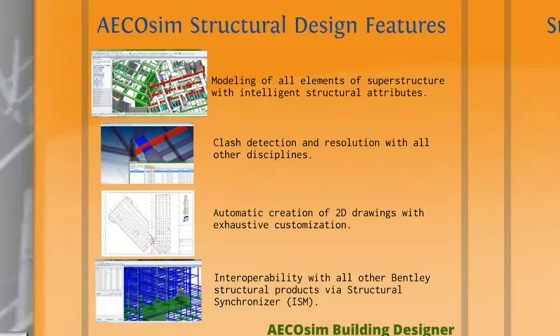applications. The second one, very important in terms of the coordination with other disciplines, and that's that you can perform clash detection between any two entities in the model, resolution as well, and that'll give us a chance to see how we stack up against perhaps the HVAC layout that's been proposed, or other disciplines versus the structural framing. The third item, of course, is generally what our deliverable is as structural engineers, and that's the ability to produce two-dimensional drawings from the 3D model. These can be customized more or less any way the engineer wants. AECOsim has a very exhaustive set of customization tools that allow you to customize your drawings how you'd like.